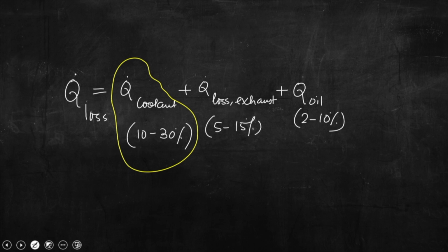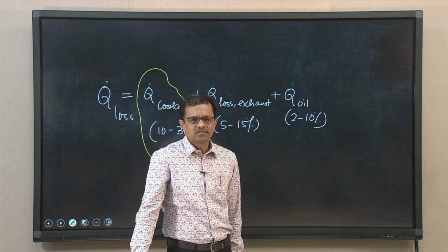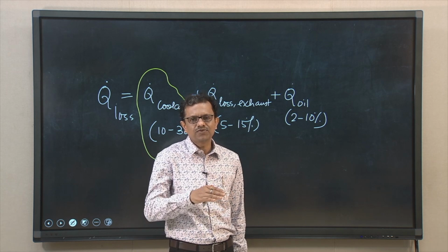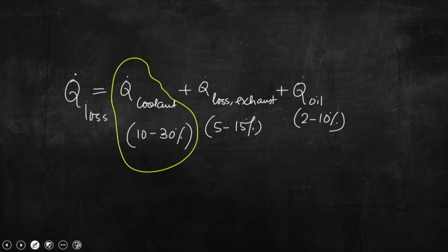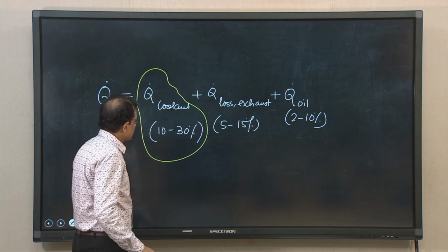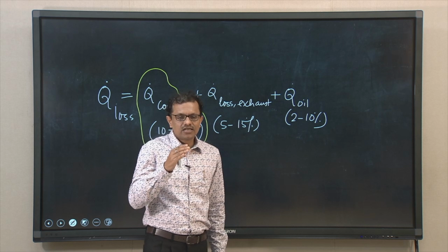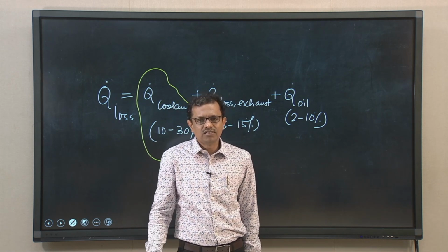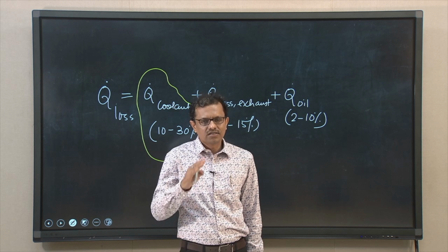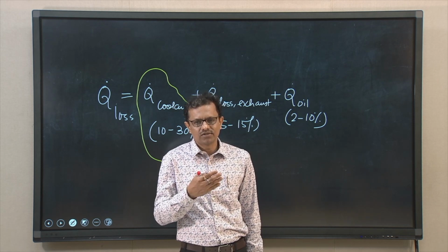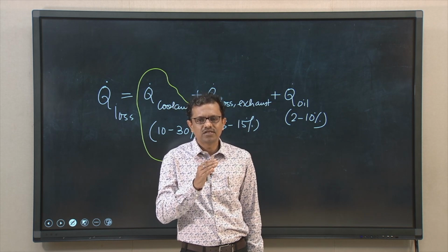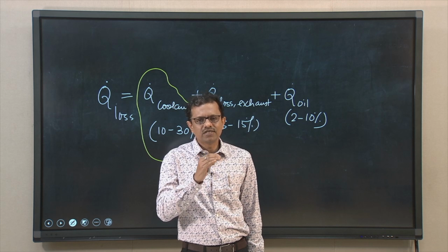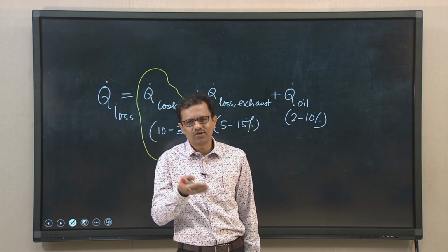Transport of energy by coolant, which is circulated through the cooling water jacket, is essentially heat transfer in the combustion chamber. We had seen transfer of energy from the engine wall or cylinder wall into the coolant. There we also discussed that the entire length of the engine cylinder is not surrounded or covered by the cooling water jacket. So there are portions from which heat is transferred directly from the outer wall of the cylinder to the ambience.